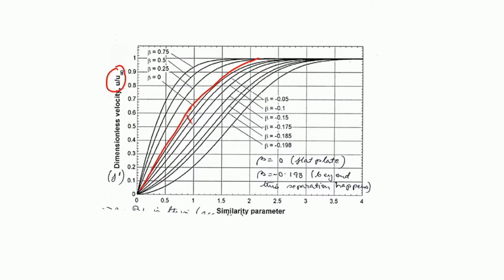In this particular direction, you can see that the boundary layer is basically sagging a little bit. That is where your beta starts to actually become negative. And in this particular direction on the other side, the beta is actually increasing. So, this corresponds basically to a diffuser, and that corresponds to a convergent nozzle.